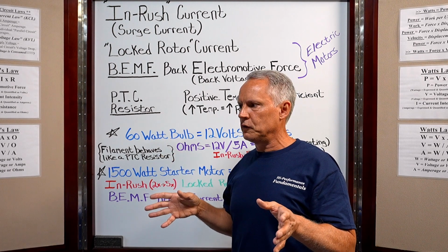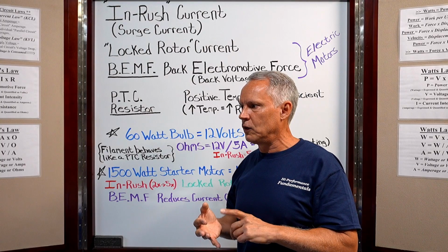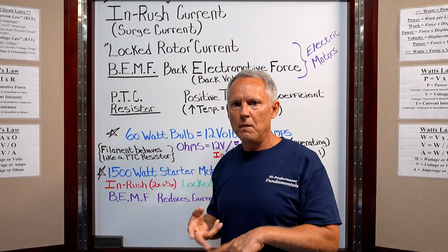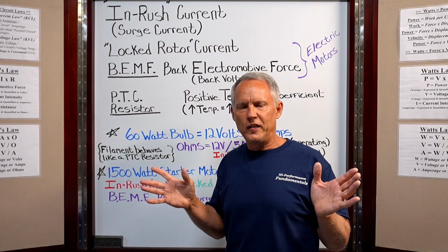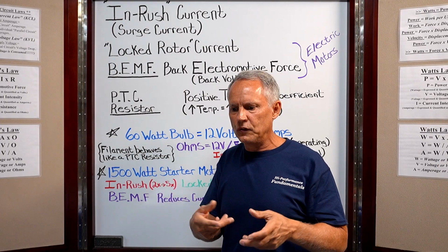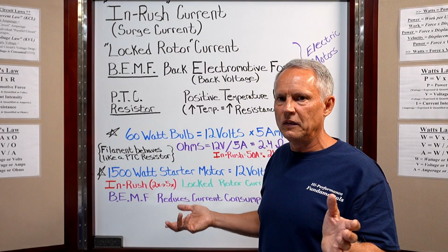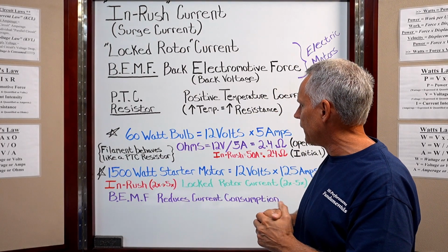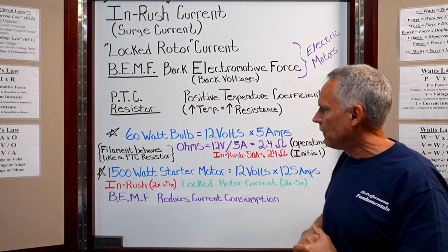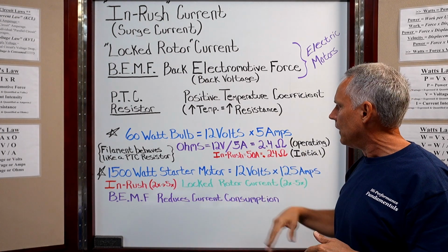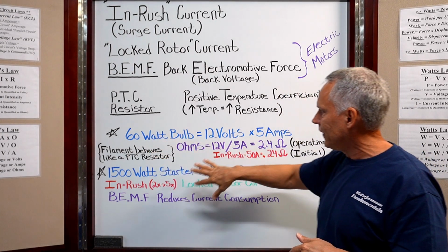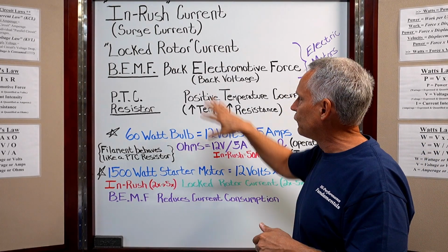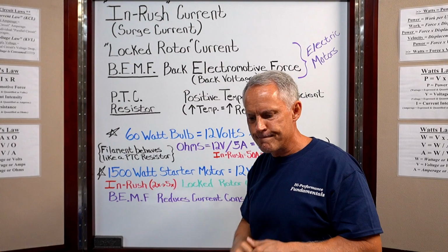But all other motors that come to mind anyway, like cooling fan motors, power window motors, power seat motors, electric fuel pump motors, electric water pump motors, you can bench test pretty much all of that and come up with a rating and use an inductive or an inline ammeter, and you'll know exactly what you're dealing with, and you can design a circuit around that, okay? So anyways, that's what I wanted to get to, and how I wanted to discuss the importance of not only calculating, converting watts into volts and amps, but also measuring it, and why it's important to actually measure it whenever possible. And these are some of the things you have to take into consideration. All right?